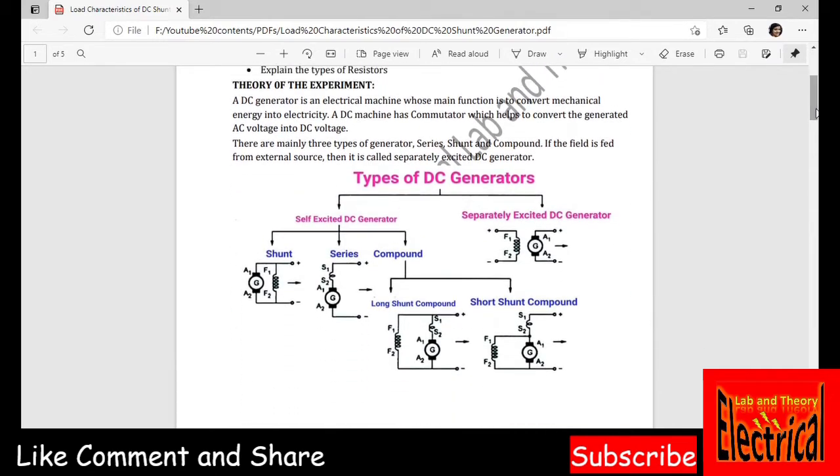Okay. So we all know that the DC generators are those generators which generate DC current. Means the generator will have some mechanical input and it will convert that mechanical input into an electrical output, and that electricity will be DC, means direct current, right? So what differs the DC generator from AC generator is the commutator. The commutator makes DC generator different from AC generator, means the commutator changes the AC voltage into DC voltage.